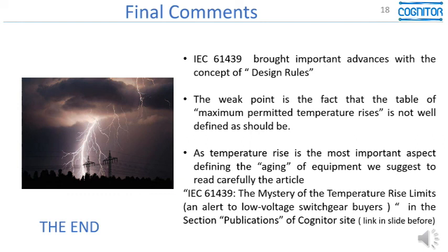The weak point of this good IEC document is the fact that the maximum permitted temperature rise in the temperature rise tests is not as well defined as it should be. This is a source of confusion all over the world. It's easy to correct, but for some reason, up to today, it's not corrected.